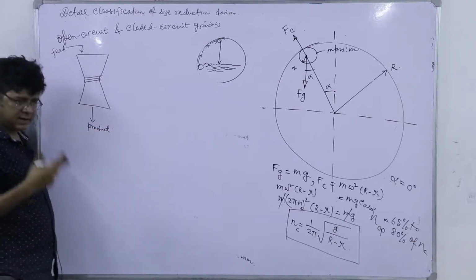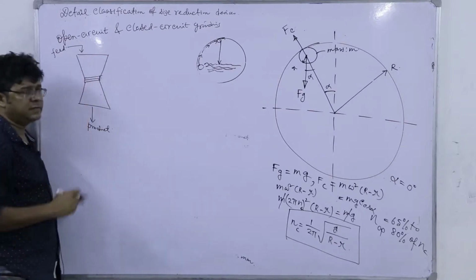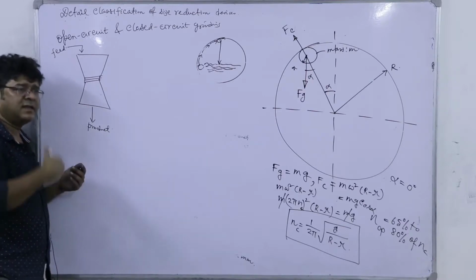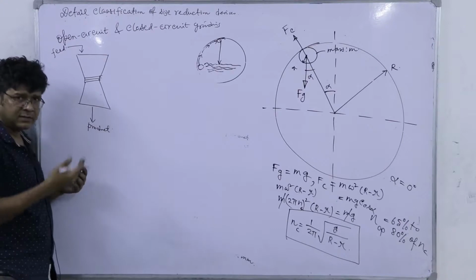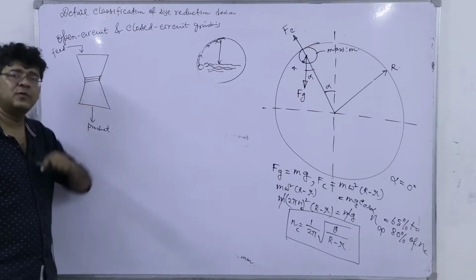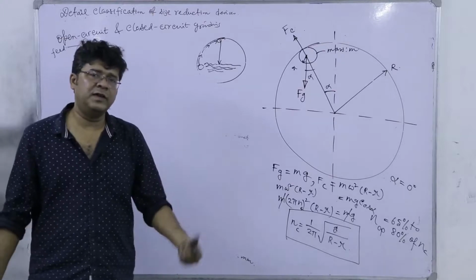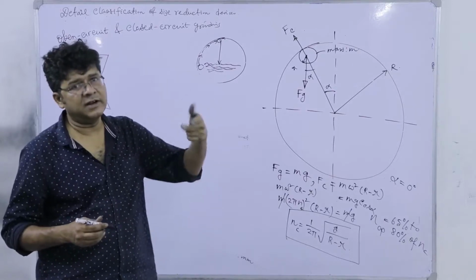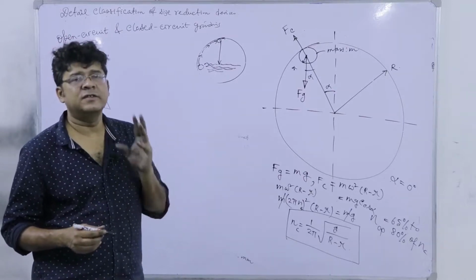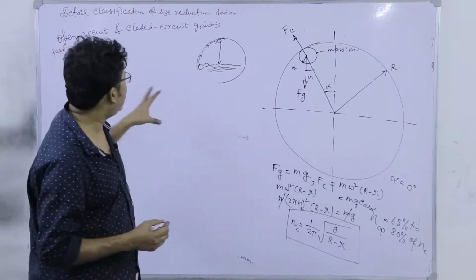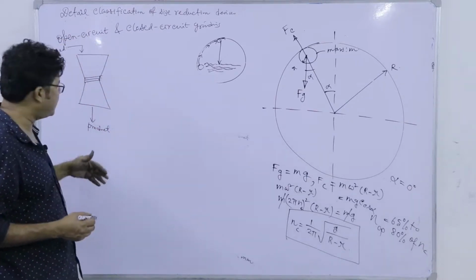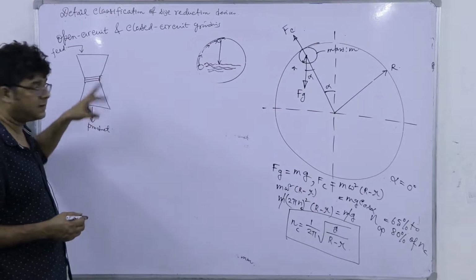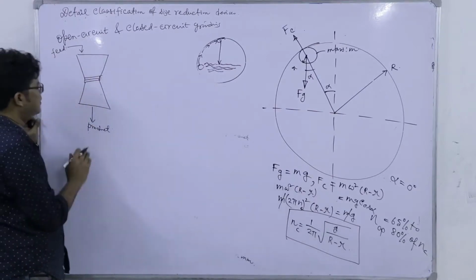Now, what happens? Inside the device, the already ground material which has attained the desired size is again circulating back again and again, because you are allowing for some residence time. Over that residence time, a large material has already reduced in size and reached the desired limit, but still it will be circulated as you are not withdrawing the product. So, this is a severe wastage of energy. And that you can minimize if you continuously withdraw the product, screen it, resolve it into 3 or 4 fractions and circulate the oversize back to this crusher.